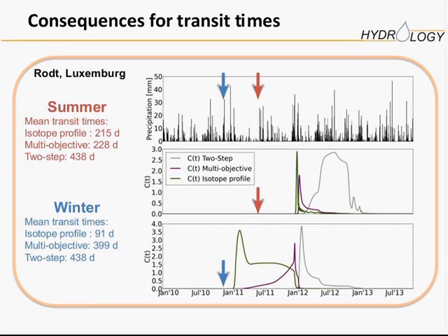So we think it's really an observation we made, but we attribute it more to the heterogeneity we have, especially at that topmost sensor that was only 5 centimeters below the soil surface. The soil was very aggregate rich, relatively loose, low bulk density, and there we may have had some preferential flow close to the sensor at that location. In the deeper ones that was not the case, but at that upper one we may have that preferential effect due to the sensor.